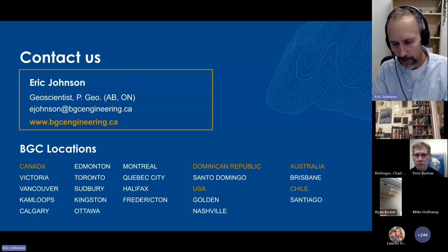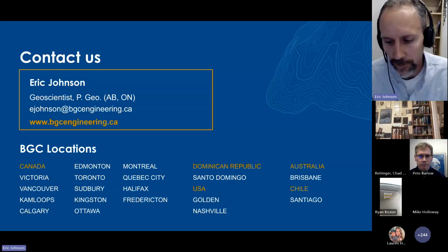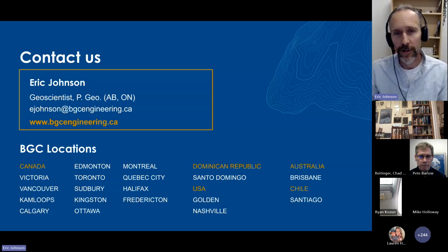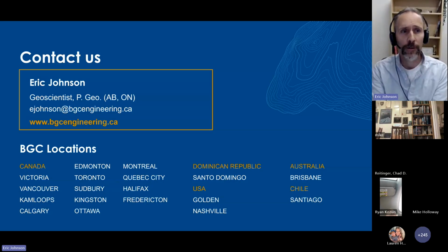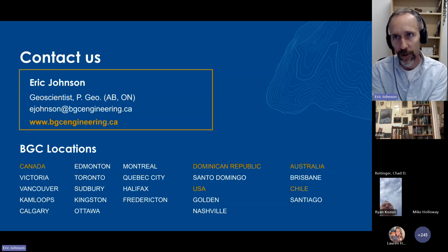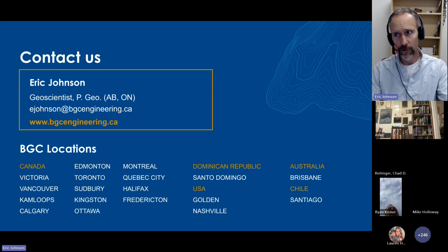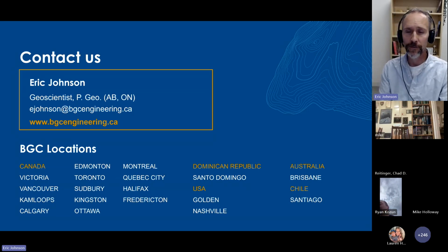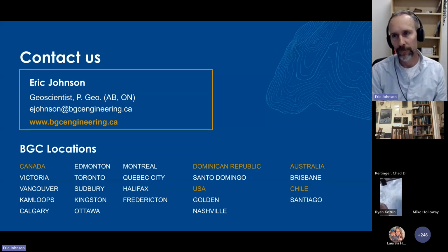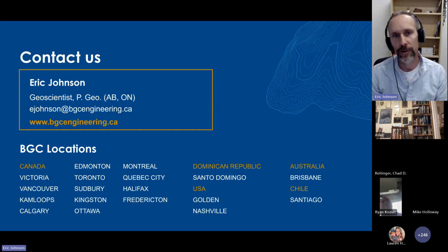Yeah, another plan that we have for this is building a database of values. So say just clays. Any of these categories that we were just looking at, we'll have a database that grows and grows of clays, and then we know that has silts, and we know the resistivity values and the seismic velocities for those values. And then we can look at a geology, even if it's a totally different site, we can have an idea of why we expect clays to have these values. Even if we've measured it at a different site, we can combine the information, like lab measurements and these measurements here, to apply that to a very new site.